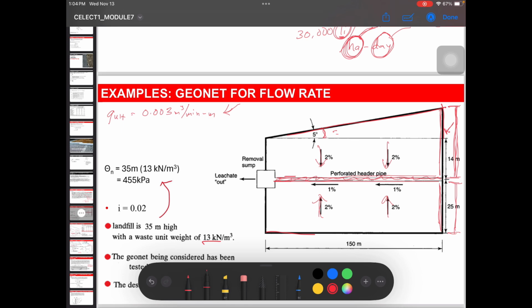So, let's find out ano muna itong distance na to. You can get that by SOHCAHTOA since tangent theta is equal to opposite over adjacent. We have angle and we have 150 meters na given dito. So, 150 itong side na to, yung adjacent side. So, we can get yung x or the opposite side na to. So, substituting tangent 5 equal yung opposite, which is what we need, and then, adjacent side is 150.